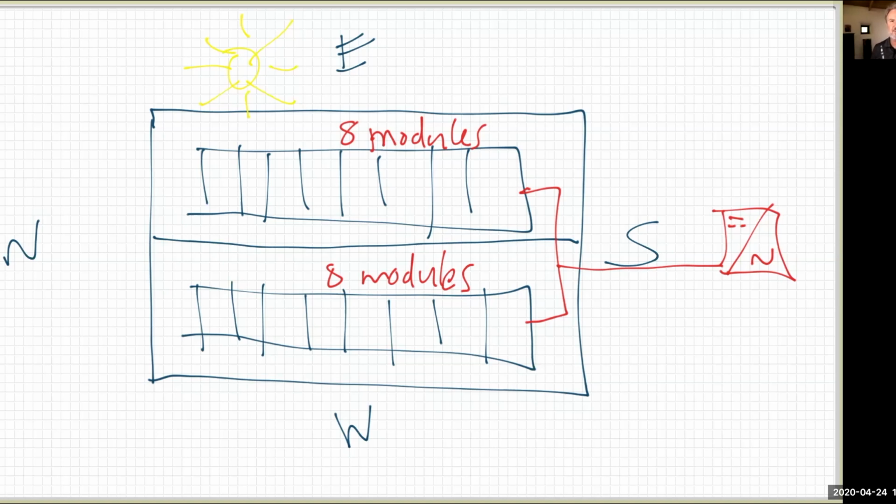So as a panel gets more sun, it heats up. So the sun is kind of the irradiance, notionally pushing up the voltage, but the heat of the sun causes the voltage of the panel to reduce, and the 2 counteract each other. So over a day, the panels on the side that aren't getting direct sunlight are operating at almost the same voltage as the panels that are getting direct sunlight. So the voltage mismatch is minimal. Now, if you still don't believe me, both SMA and Fronius have written academic papers on this and proven it. Both those companies sell dual MPPT and single MPPT inverters, so there's no commercial reason for them to try and push this. They're just pointing out that it is a lucky coincidence of physics.